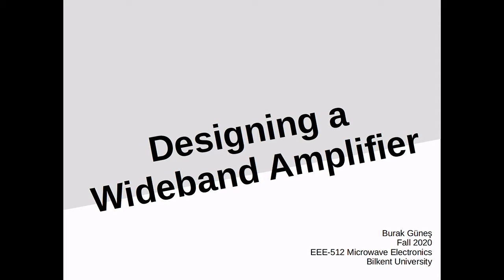Hi, this is Burak Güneş. In this video, I will walk you through the basic design and manufacturing steps concerning a wideband amplifier. This amplifier is intended to use in the 1.5 to 2 GHz bandwidth, providing a 10 dB flat gain with the worst case return loss figures of around 13.5 dB.